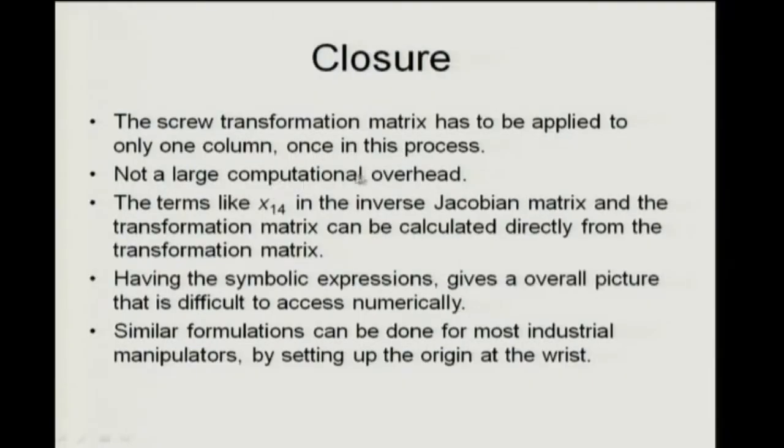Oh, I seem to have jumped ahead. So just to review, you have to apply it to only one column, once, in this process, not a large computational overhead. Terms like x14 in the inverse Jacobian matrix and the transformation matrix can be calculated directly from the DH matrices.